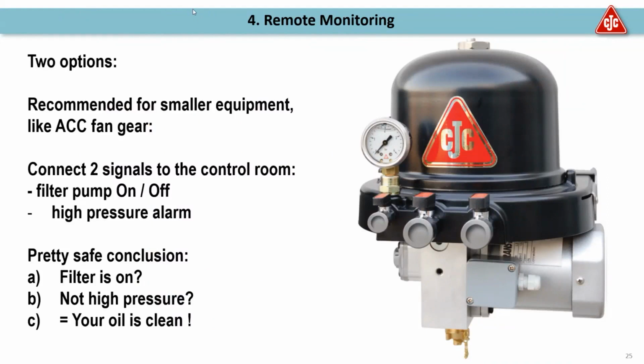So what we recommend at a minimum is connect 2 signals to the control room, and that would be filter pump on/off and a high pressure alarm. Because it is very safe to assume that when the filter is on and it has not reached high pressure, your oil is clean.